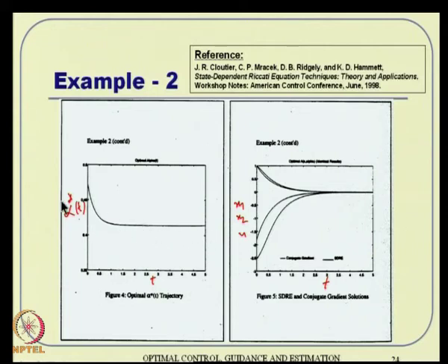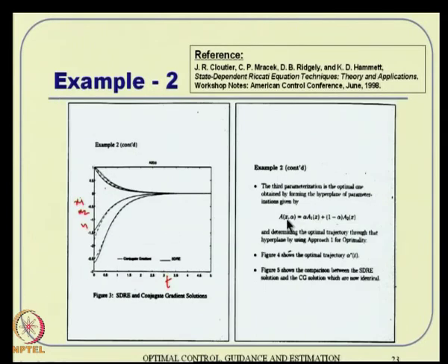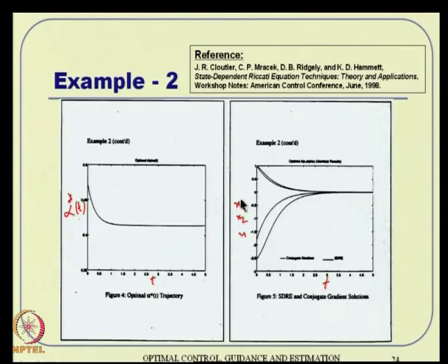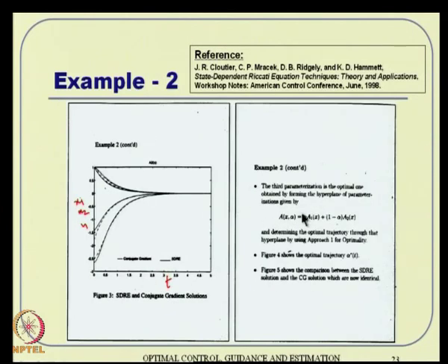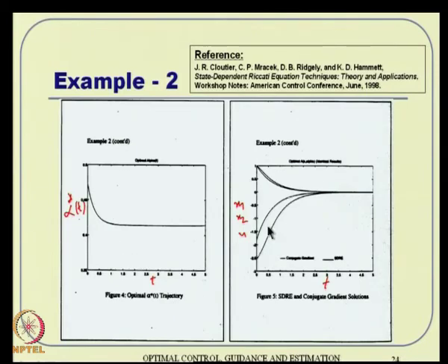So you keep on computing alpha star, and then you compute an A which is a function of that alpha, and then apply SDRE using this newly constructed A matrix. Then this is what the result is, which is very neat to see. That demonstrates that this design approach has an additional degree of freedom, using which we can go very close to optimality.